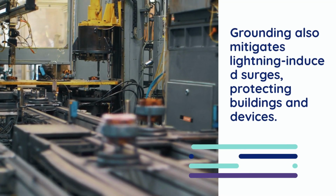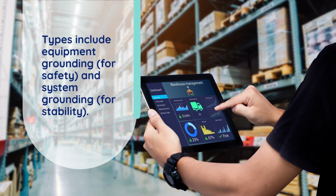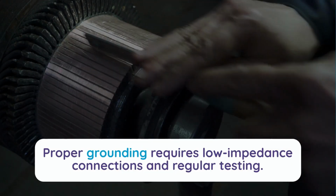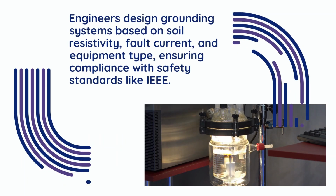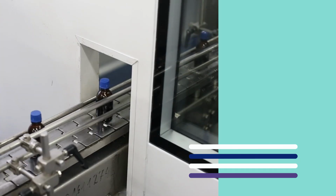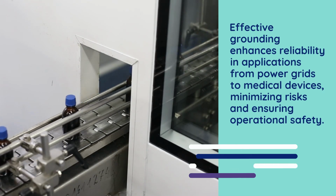Grounding also mitigates lightning-induced surges, protecting buildings and devices. Types include equipment grounding, for safety, and system grounding, for stability. Proper grounding requires low-impedance connections and regular testing. In industrial settings, grounding prevents static buildup in hazardous environments. Engineers design grounding systems based on soil resistivity, fault current, and equipment type, ensuring compliance with safety standards like IEEE. Effective grounding enhances reliability in applications from power grids to medical devices, minimizing risks and ensuring operational safety.